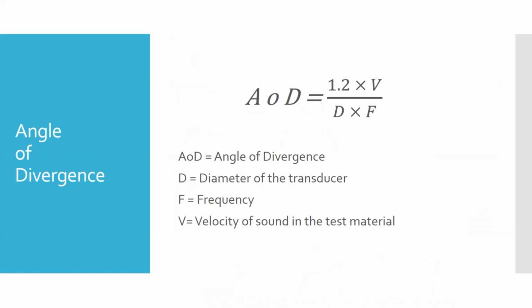So aluminum, the typical velocity in aluminum is, and I'm doing this in, normally we will be doing our stuff in imperial units, but the calculations go a lot easier for learning in metric because they just play nicer. So in aluminum, the typical velocity is 5,100 meters per second.